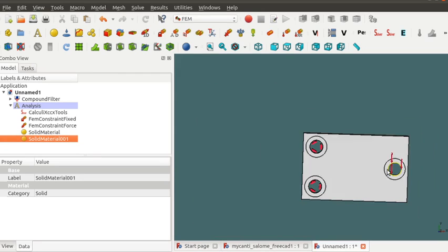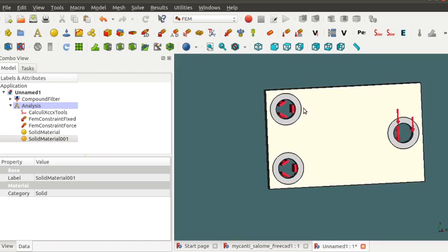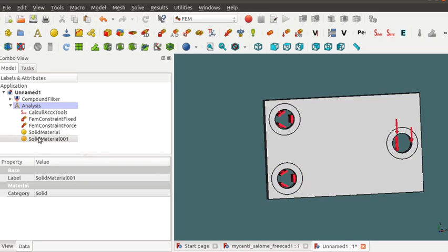Why are we doing this? This is just to get a group of nodes. In performing optimization, we have to tell the algorithm that this region has to be excluded. So in order to extract the group, we are creating this step. Then the next thing is to mesh the object.